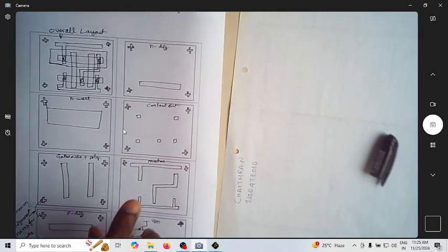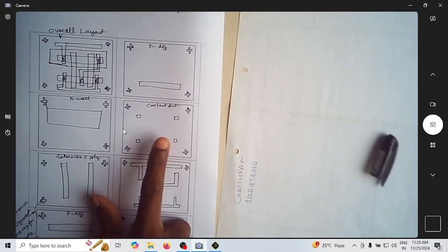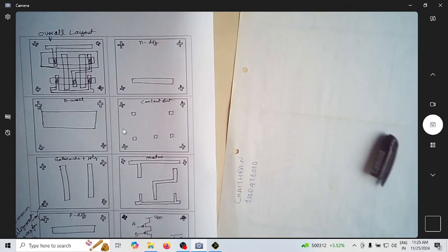So this is my thin oxide mask, and then we're going to have the P diffusion mask, and then the N diffusion mask, and then we have the contact cuts for connecting the metal to the diffusion points, and then we have the final metal deposition so that you can take out the output.